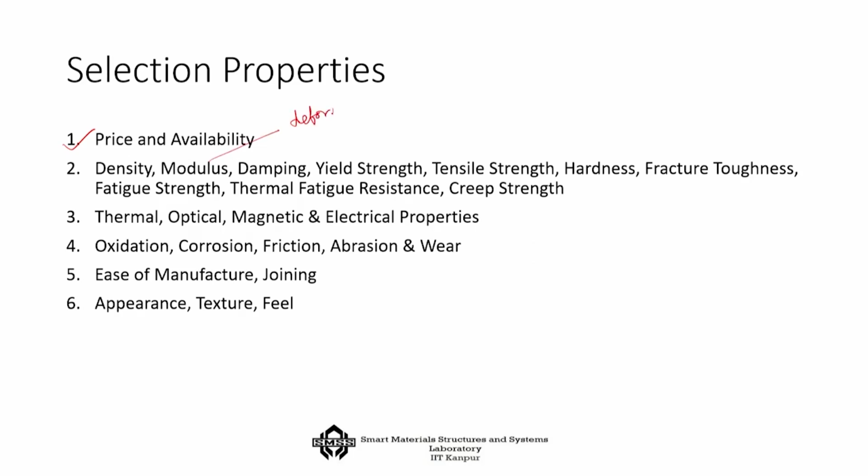That means, if the system is having low modulus of elasticity like polymer, then I would be able to deform it. See, so easily I am able to deform it, because it has a low modulus of elasticity. The same force, if I apply for this pen, I won't be able to deform it, you won't be able to see. It will deform, but it will deform in a microscopic scale. So, it will be having a higher modulus of elasticity. Maybe the difference is that this would be made of, let us say, low density polyethylene, and this will be made of a high density polyethylene. So, the modulus of elasticity would change.